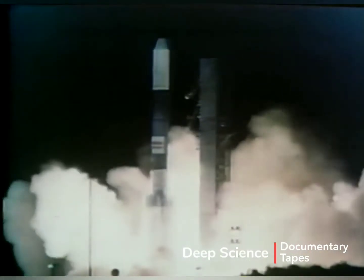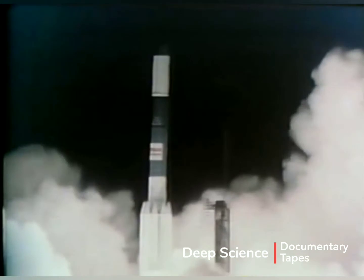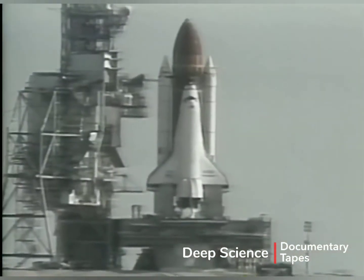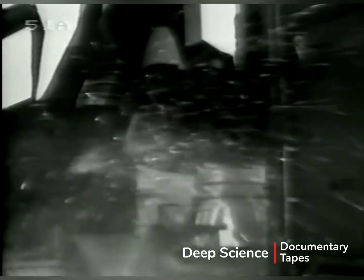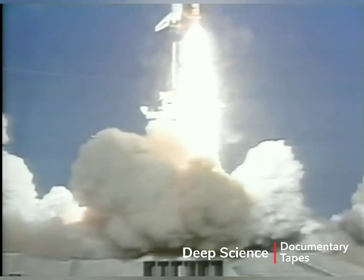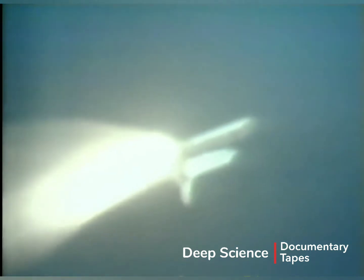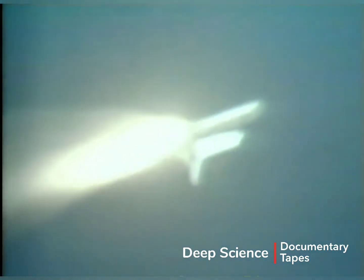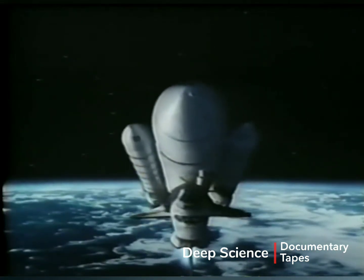Staging offers the advantage of discarding weight when it is no longer needed. The space shuttle is a two-stage system. At liftoff, the 2 solid rocket boosters and 3 space shuttle main engines are all producing thrust. After approximately 2 minutes of flight, at an altitude of 25 miles, the fuel in the solid rocket boosters is depleted and they are jettisoned.